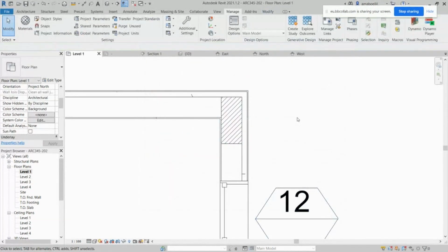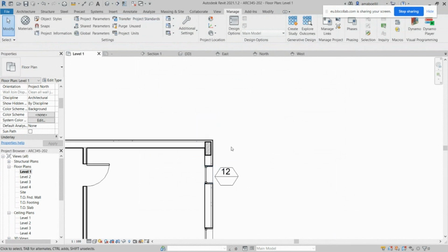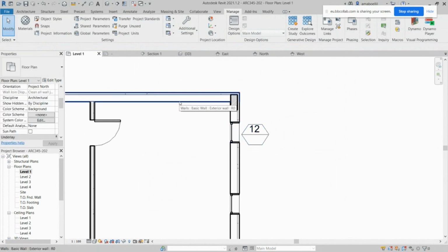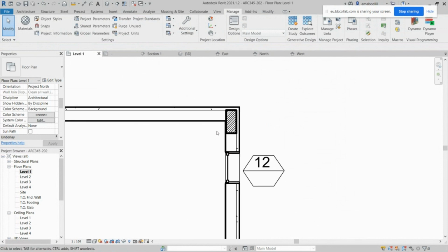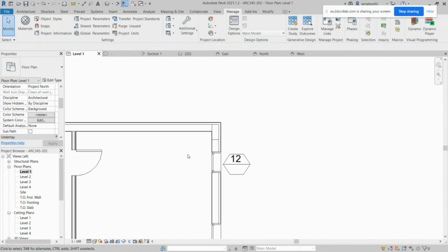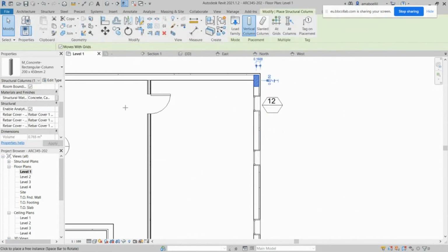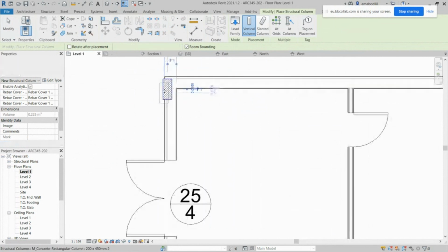So I said that I don't want to see in projects columns that are not hatched, not shown strictly. You can pick this and see that this is how the quality of the drawing would look even before adjusting the dimension, because what you cut through has to be the thickest, and then pattern or doors and windows that are secondary in this case are going to be a little bit lighter in line thickness. After that, we can pick this and create a similar one for sure. We can place it similar to what we did, and then place our, I will just do that here.